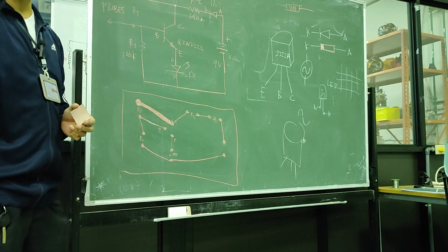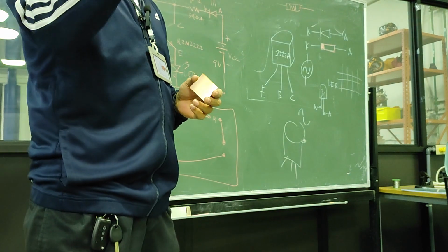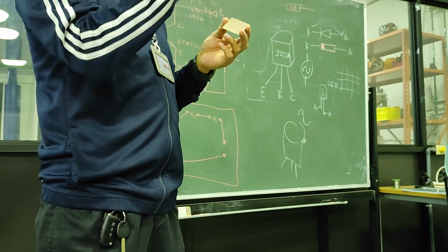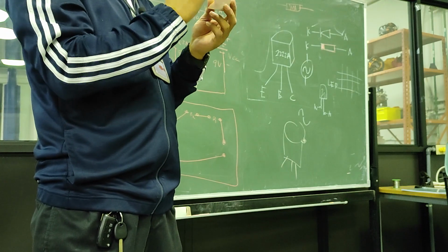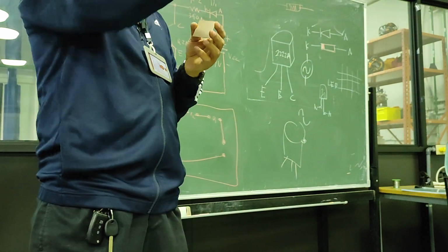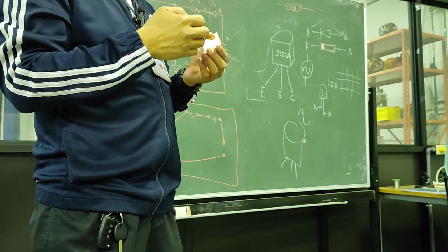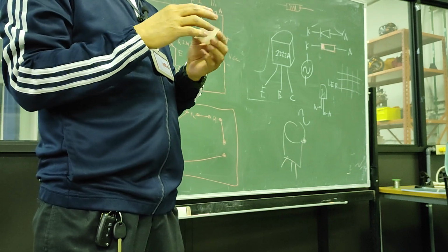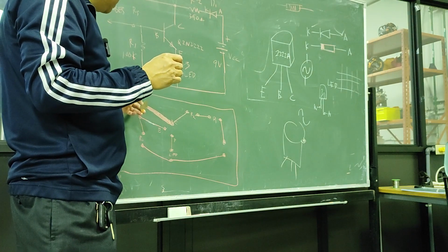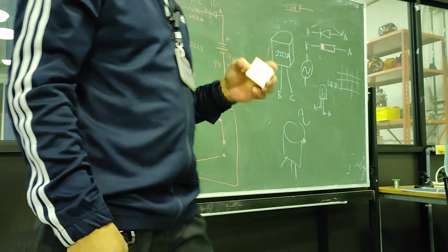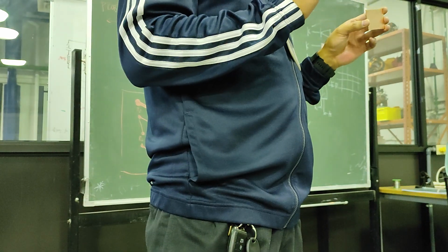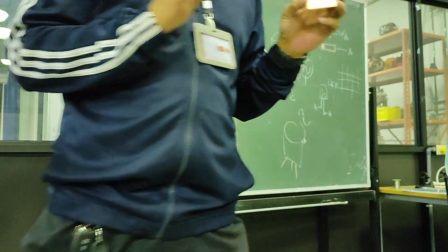Because now we are using the manual method, I'll give you a special pen later. The special pen is a fixed pen, to be permanently written here, then we will use some process later. Then drilling and so on. So again, take note: as much as possible, make the pads bigger and the traces thicker. All right? Any question? Is it clear? Yes. Clear now? Yes. That's okay.